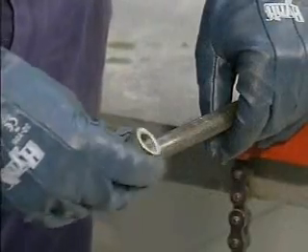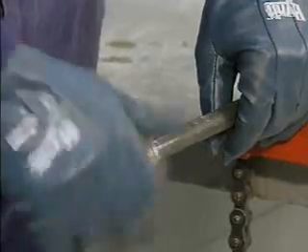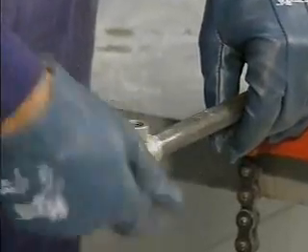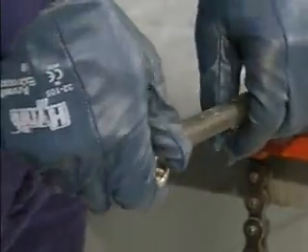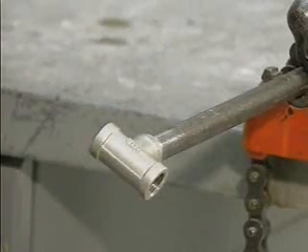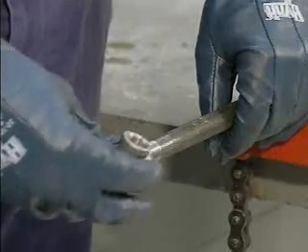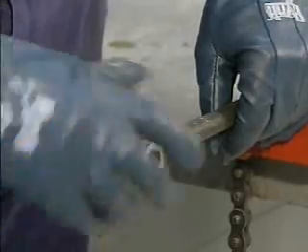Threaded joints, or screwed joints, are made by screwing the outside threaded end of a pipe into the inside threaded end of a pipe fitting. Threaded joints have a specified engagement depth. The engagement depth is the distance that the pipe must be turned into the fitting. The engagement depth requirement must be reached for the joint to be properly threaded. As pipe size increases, engagement depth also increases.